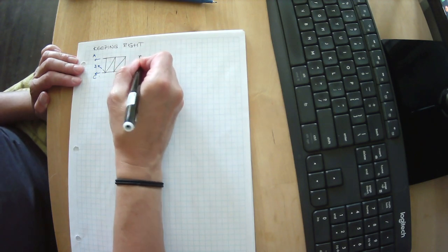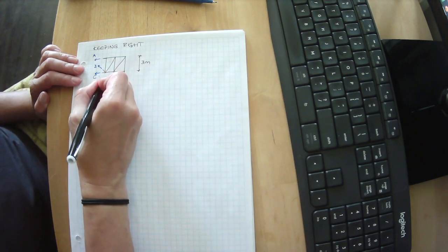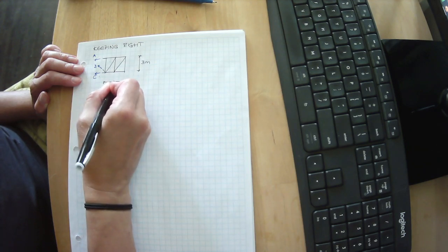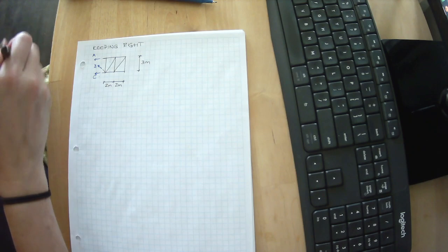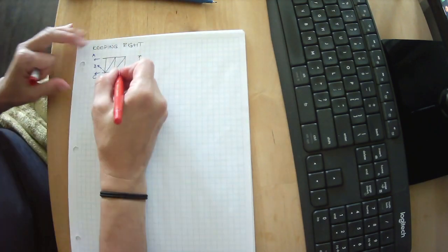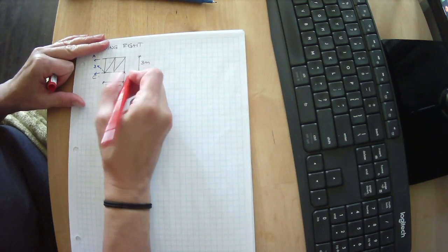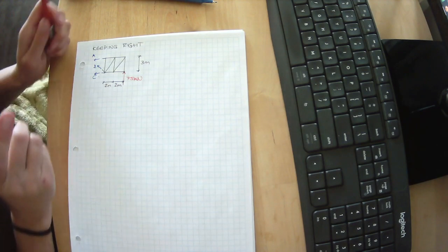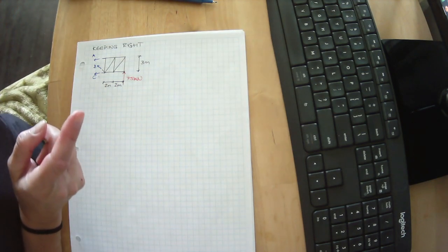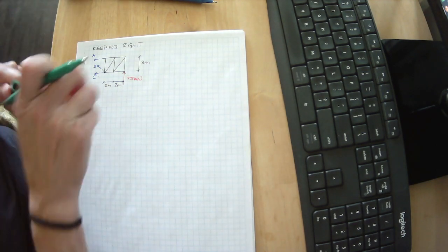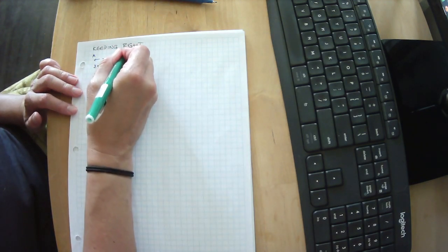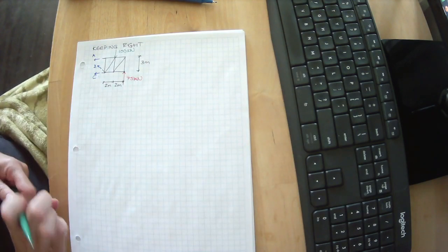We know that this is 3 meters, and this is 2 meters, and this is 2 meters, and we had solved this previously to know that this was 75 kilonewtons of reaction right there, but when we cut this side, check it out. We also have 100 kilonewtons of load.